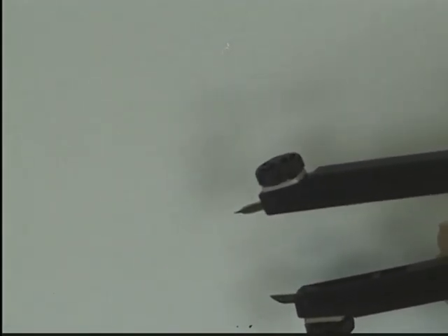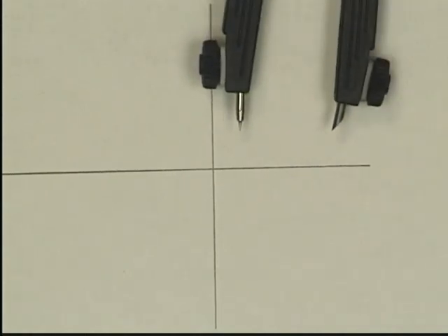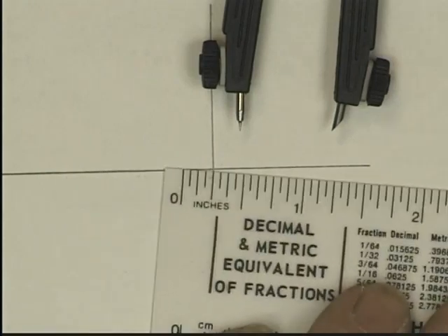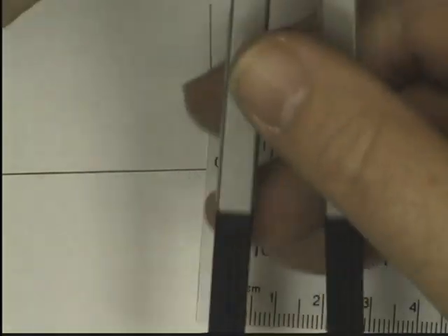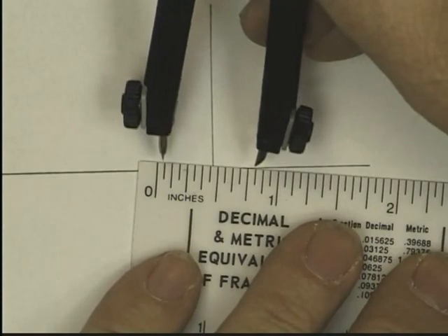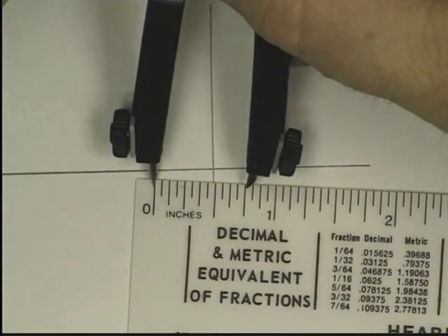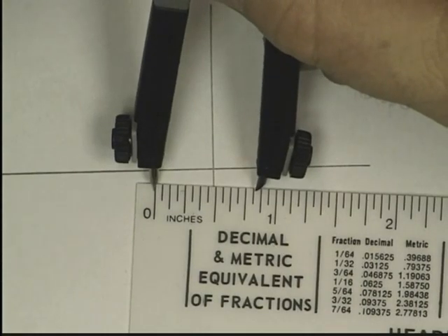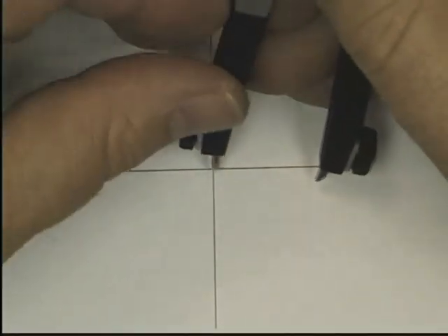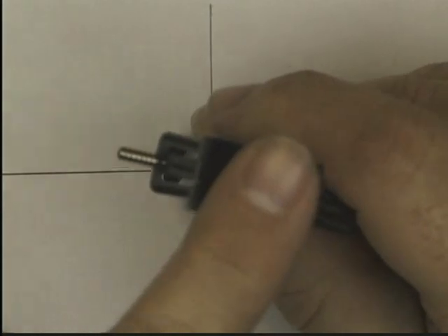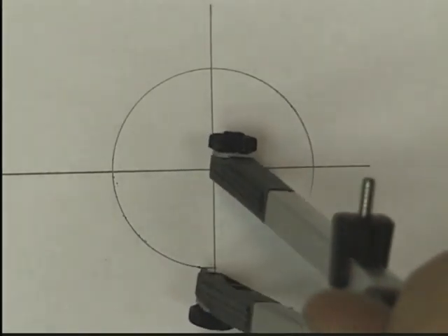Now that I've got the compass all sharpened up, I can draw some circles. How big is a circle going to be? Well, circles are measured by diameter, but when you're using a compass, you have to adjust the compass to the radius of the circle. So you take a scale and you put the point of the compass at the 0, and I'm over here on this little knob now. I'm going to adjust with that adjustment knob until I get this point exactly at the radius size, which is half of the diameter that I want to make the circle. Once I've adjusted that, then I'll very carefully put the point right in the crosshairs, right in the crossing center lines, and then I can swing this around and draw either a full circle or an arc.